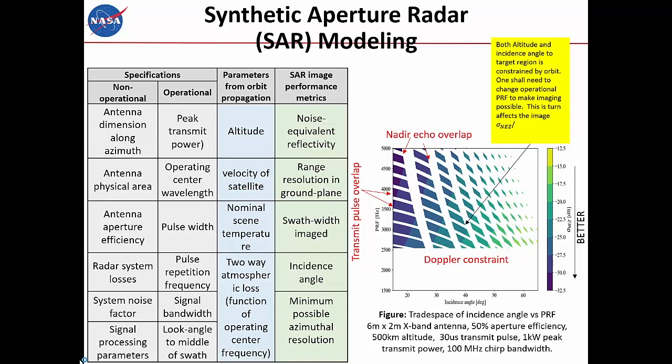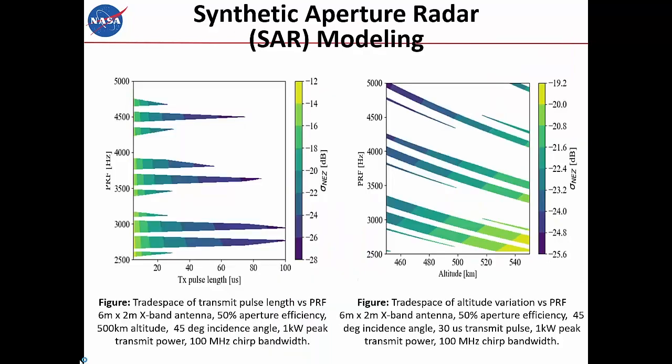So this is just in single instrument design. And then we translate this into multiple instrument design and then fly all those instruments in parallel in space. So in the single instrument design, for example, our tool is capable of showing the trades between PRF, which is pulse repetition frequency, and the pulse length in terms of signal to noise ratio. And all the white space is stuff where no design exists. So when we pick a design for a specific instrument, we have to choose a design in the colored areas. And at that point, I ask myself, what PRF am I happy with, and what do I need as pulse length for which I get a specific signal to noise ratio.